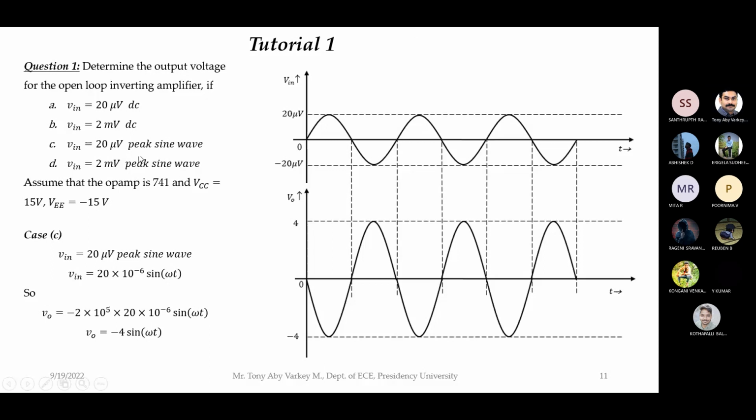This is sine 0, which is 0. This is sine 90, maximum 1. Then this is sine 180, that is 0. And this is 270. This is 360, one full revolution. So you can see that if you shift this signal 180 degrees, you will get this. The shape will be like this. That is why it is called a 180-degree phase shift.